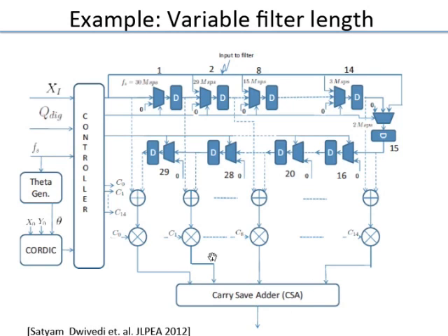Here is something which we will discuss later. There is a carry save adder tree. This is used when you want to add a number of numbers together. Typically when you add 2 numbers, the simplest way of adding is what is called a ripple carry. Like how would you do it by hand? You start from the least significant digit, you add, carry, and so on. So the carry keeps rippling. In a carry save adder, you don't explicitly add the carry till the very end, and it's very useful when you have a number of numbers you want to add together. So you do it in a carry save fashion. We'll look at it later in the course.